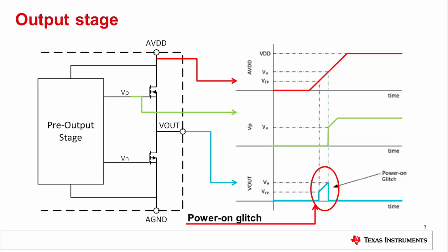So what can be done to reduce this effect? There are only a few ways to reduce power on glitch. A filter will only spread the energy out over time, but will reduce the amplitude. However, in most cases, the energy is so large that this method is still unacceptable, as the output will take too long to settle back to the desired voltage.